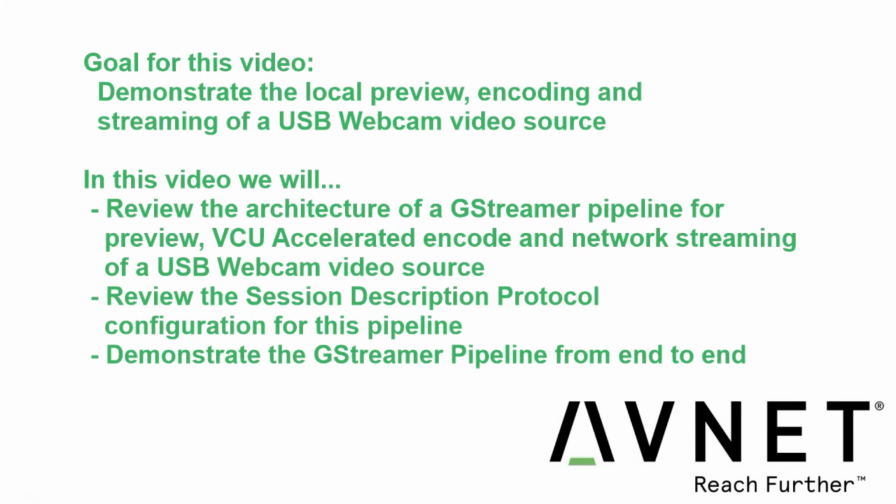In this video, we're going to demonstrate that local preview, but also the encoding and streaming of the USB webcam video source. We're going to highlight the architecture of the GStreamer pipeline for previewing and accelerated encode and network streaming of webcam video. We're also going to review the session description protocol configuration for this pipeline, which is necessary for subscribing to the network stream on the remote end. And then we're going to finish that up with a complete end-to-end demo.